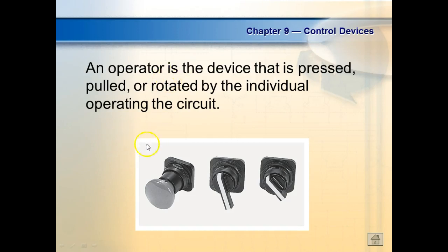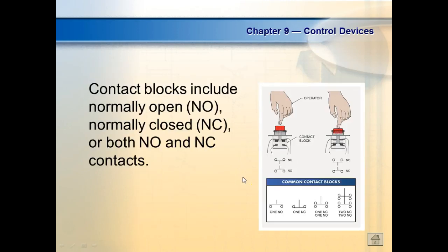So this is a push button on the side, right? These are selector switches. These are push buttons. These would be what we call a single pole double throw, right? Everybody okay? This would be normally open. This would be normally closed. These I got them drawn real close together. This would be a what? Single pole double throw, right? Everybody okay? Is that a double pole? This is a double pole double throw right here.